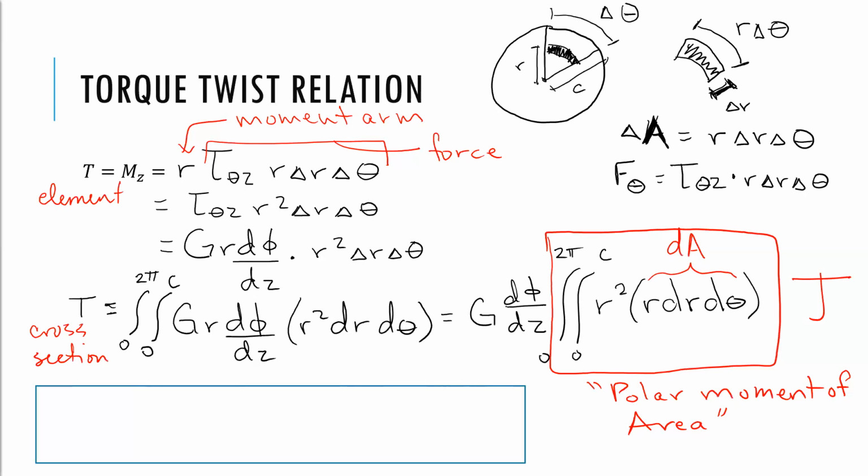Or second moment of area, moment of inertia, something like that, right? I, you had Ix, you had Iy. Well, if you add Ix to Iy, you get J. And J is your polar moment of inertia. You can calculate it by taking the integral of r squared over the area. And it's typically important for cylindrical shapes. Please go back and get very familiar with I. Right? I is important.